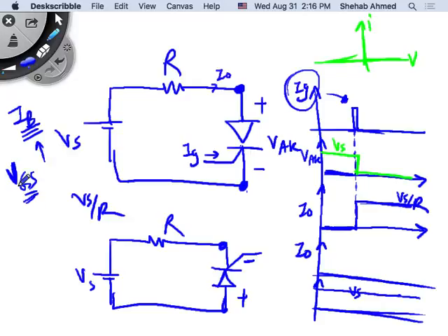And what is the device made of? You had the gate, then an insulating material, and then the channel. Remember, this looked like a capacitor when you took 325? Capacitors, as soon as you place a voltage across them, draw some current to charge the capacitor and bring it to a certain value of voltage. And then that's it. As soon as the capacitor is at the same voltage as the voltage source, no current will flow anymore, which is one of the big advantages of a MOSFET versus a BJT type device.